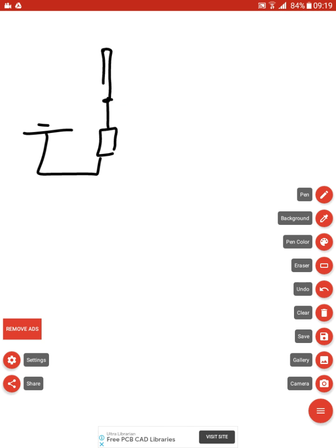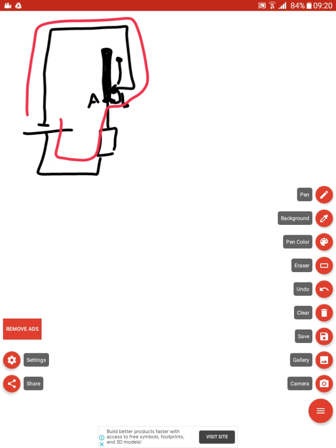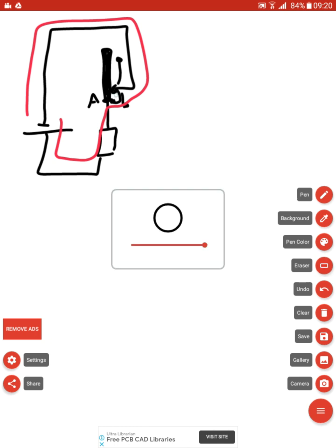Another way of changing the distribution of voltage: we have here a constant resistance and we bring a variable resistance wire, of variable length. This is the wire and this is a movable point, so you can move it up and down, okay? If the wire is at this point, let's say point A, the current will pass through a smaller path like this. So here there is no resistance, so all the voltage will be given to the constant resistance.